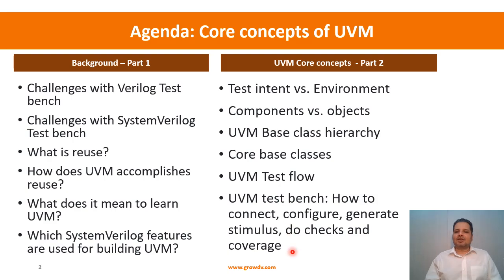And then the main thing for this session, which is a key focus, the climax of this session, which comes towards the end, is we will understand the overall test flow. This is the key thing: how do you connect a DUT, how do you configure it, how do you generate the stimulus, how do you do the checks, and how do you do the coverage in UVM?